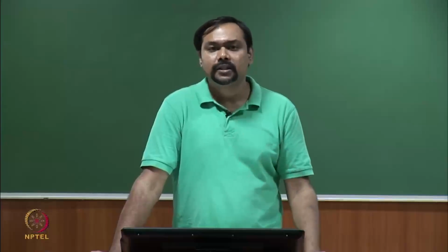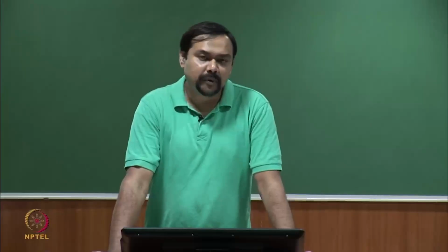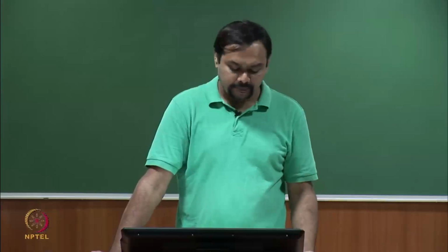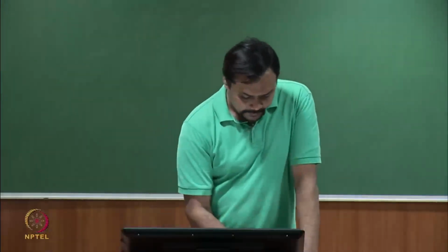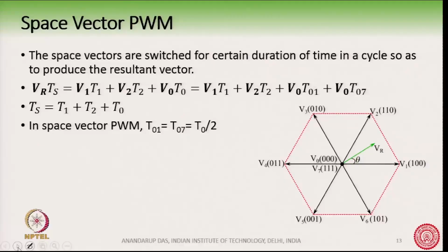This technique of switching the 8 space vectors in such a way that the resultant voltage or current is realized is called the space vector PWM. So, it is a switching strategy by which we can appropriately switch the vectors for certain time durations. So, the space vectors are switched for a certain duration of time in a cycle to produce the resultant vector.